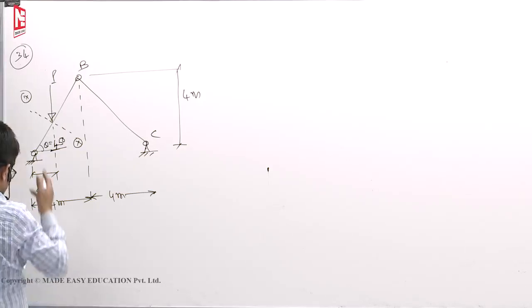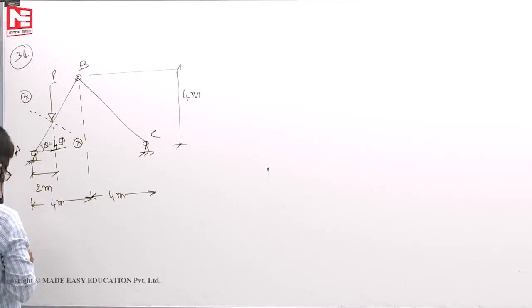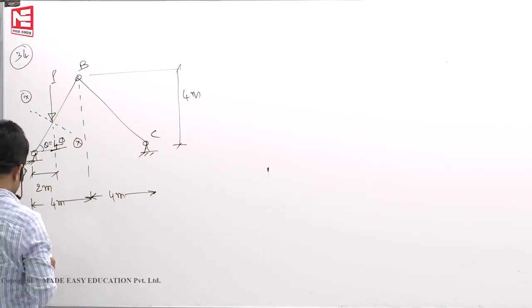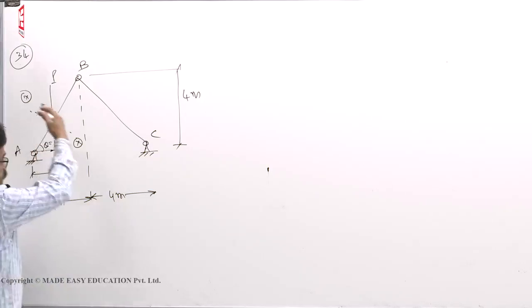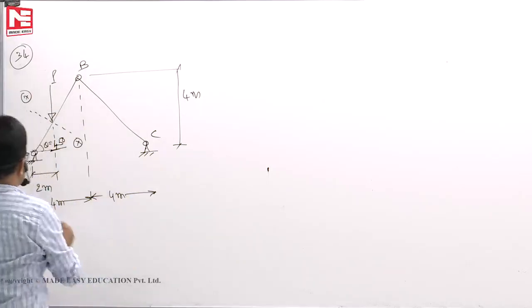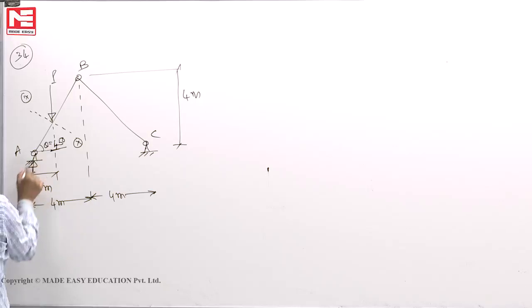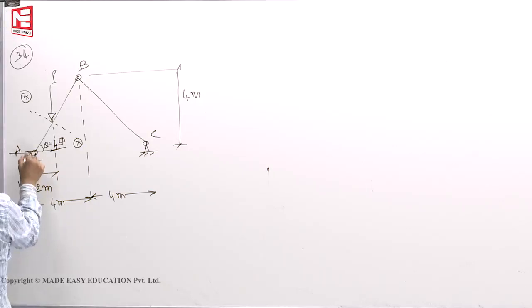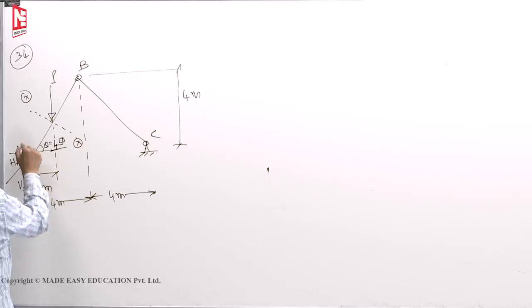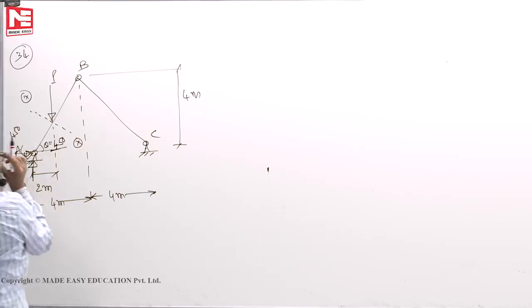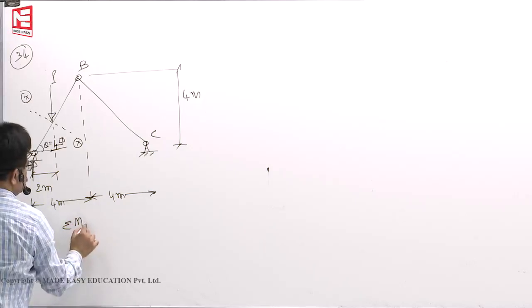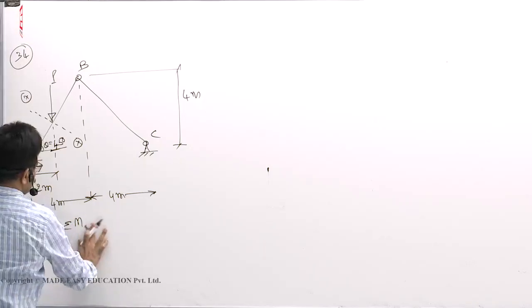It is a 3-hinged frame shown in the figure. Shear force, when you are calculating, must be parallel to the cross section. For that you require VA and HA. Then you can find the components. This angle of inclination is 45 degrees. Then first find VA. Find moments of all forces about C.